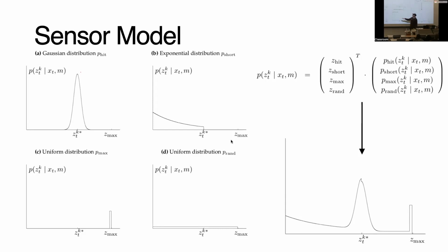Well, this would be like random people walking in front of our robot that gives us a bad measurement, right? A measurement not of the environment, but a measurement of something that's not the map we're interested in, right? So there's some probability that someone walking in front of our robot gives us a spurious, incorrect measurement for that sensor reading.